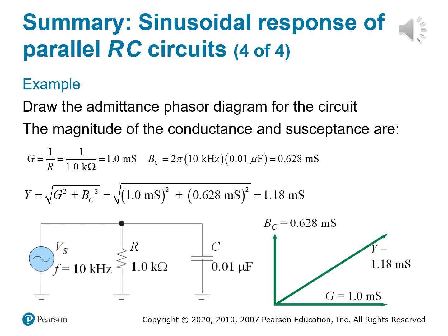And I hope by now you're starting to be able to see that since these two are going in opposite directions, when we're adding those imaginary parts, they start canceling each other out. All right. So this is one of the ways to correct for power factor, if you can start seeing that or thinking ahead. All right. So again, we just flip the orientation based on the component's behavior.